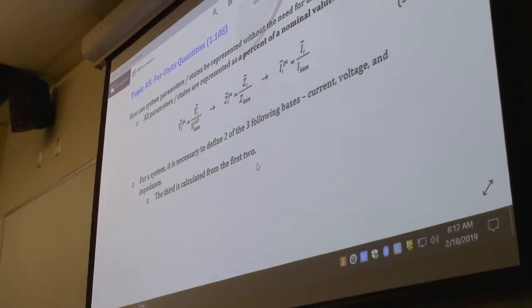It's the manufacturer's rating, or it can be another rating that you're using in order to get units, components within a system to agree with one another. One of the things that we'll see is when we use per unit analysis, or per unit values, all of the components need to share the same power base or same power rated value in the system in order for the calculations to work. So we have to do conversions sometimes.